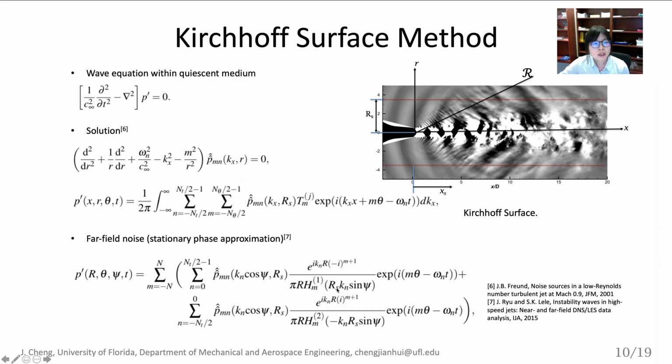Based on the LES database, we can predict the far-field noise with the Kirchhoff surface method. We believe that outside the surface, the nonlinear and viscous effects can be neglected. Therefore, we can use this wave equation to predict the far-field noise, and we apply the method from Freund by transforming the wave equation in terms of time, streamwise direction, and azimuthal direction.